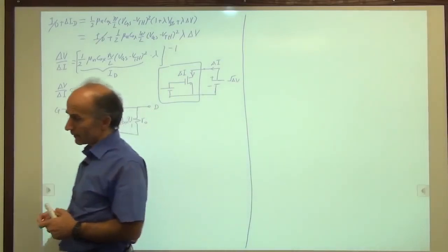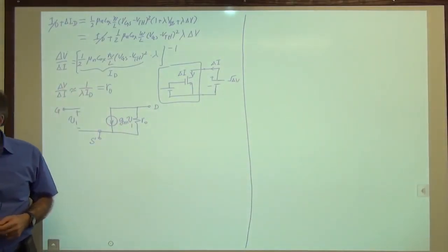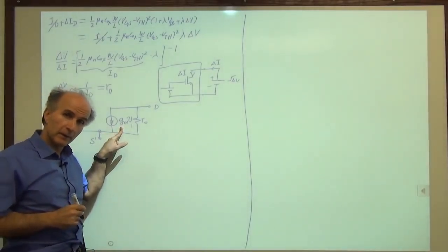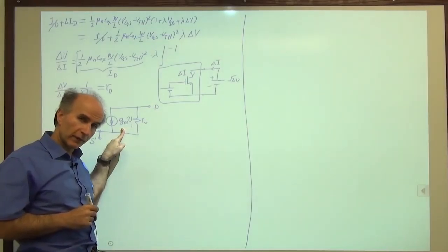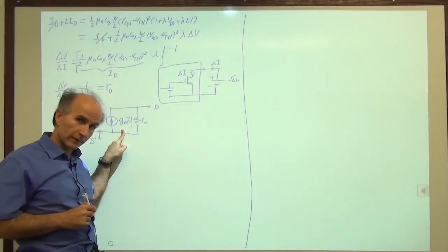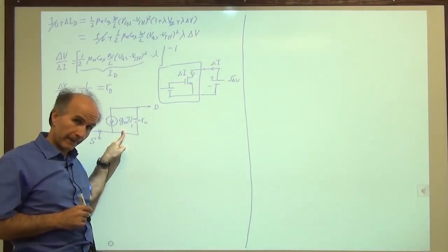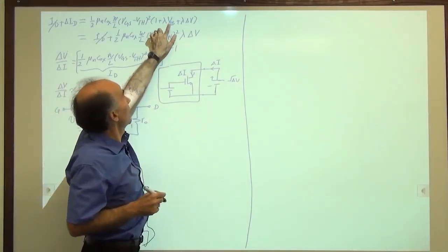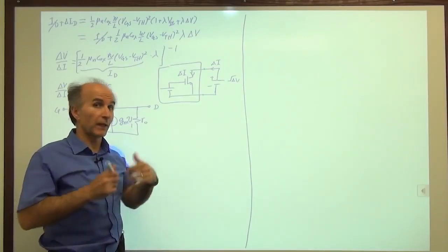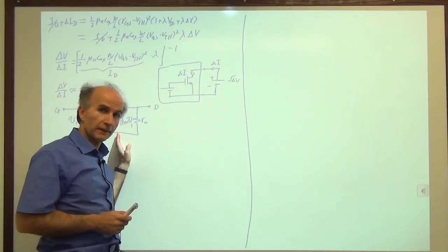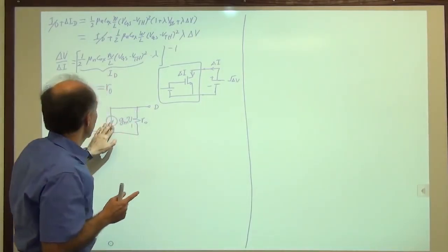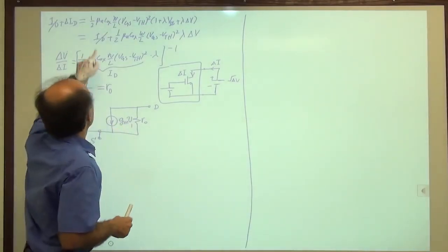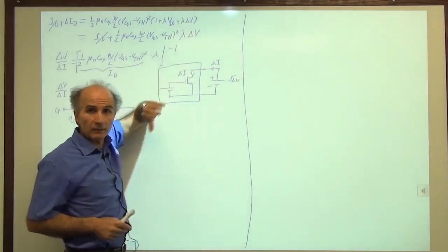All right. So based on this model, now we can analyze various circuits. Now, remember we had three equations for gm before? And they were obtained by taking the derivative of the large signal model with respect to VGS. But in that large signal model that we used to derive gm, we did not include lambda VDS, if you remember, right? So we neglected channel length modulation, we found gm, and we used it here. So now the situation is a little more complicated, right? Because we see that gm itself may also be affected by channel length modulation. Because I have to take this equation up to here, and then take the derivative with respect to VGS.